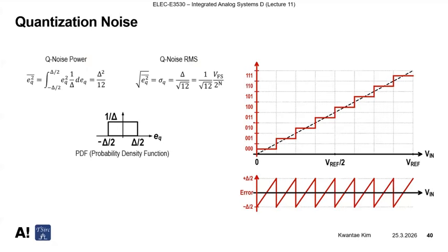Then, if you remember how we analyzed noise in the previous Basics of IC Design course, we get the power of our noise. Because in many cases, noise has a certain amount of mean value. If we just take the average, then all of the AC components are averaged out, and we face the situation that noise is zero. That's not true.